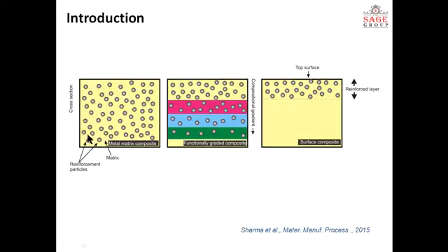See, in this figure you can see that the reinforcement may be ceramic particles or metallic, whatsoever, different from the matrix material. Suppose for example the matrix is an aluminum alloy, and the reinforcement is silicon carbide. So silicon carbide ceramic particles are mixed in this aluminum alloy to make a metal matrix composite. These are the primary composites used in many applications, like pistons in internal combustion engines.